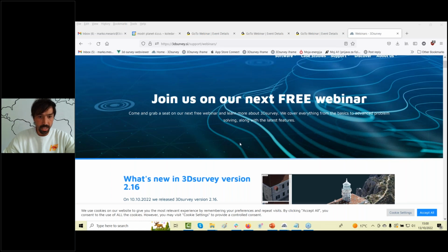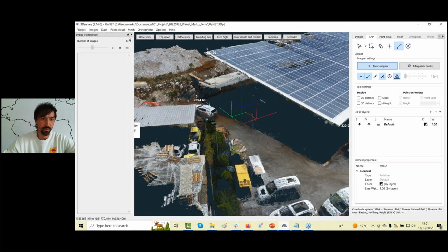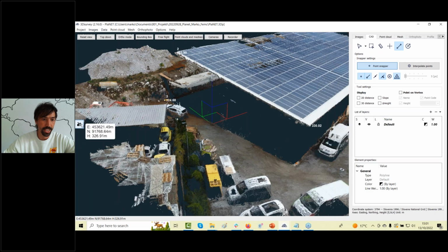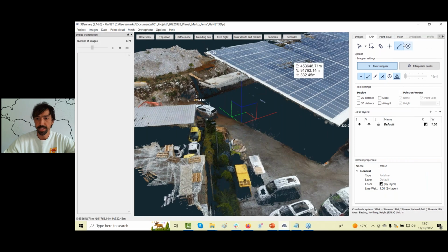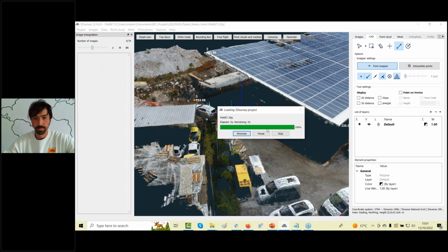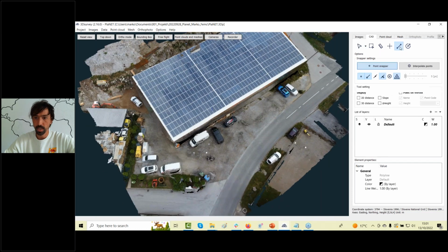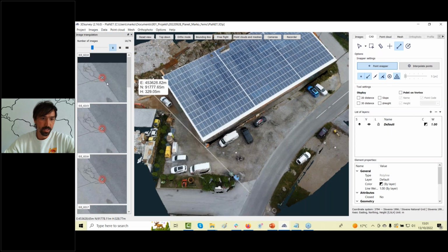Okay, another question. Jerry Hammond is asking, how did you turn on the images to select image features for CAD? So actually the images are turned on automatically, immediately when you select a drawing tool. By default they are hidden. I will turn that back on if I click this icon, but otherwise, if you start a new project, so let me open this project again, that we will start from default. When you are in the CAD tab and you select a draw function and click the first button, this window pops up immediately.